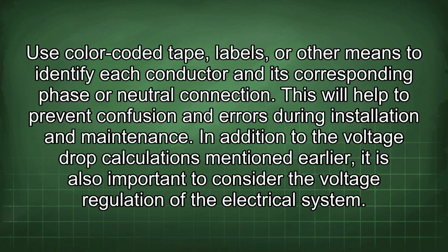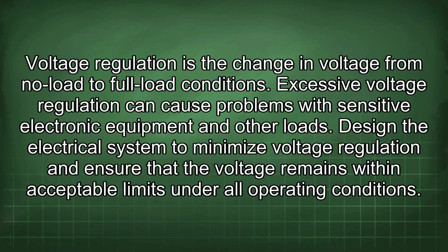This will help to prevent confusion and errors during installation and maintenance. In addition to the voltage drop calculations mentioned earlier, it is also important to consider the voltage regulation of the electrical system. Voltage regulation is the change in voltage from no load to full load conditions. Excessive voltage regulation can cause problems with sensitive electronic equipment and other loads.